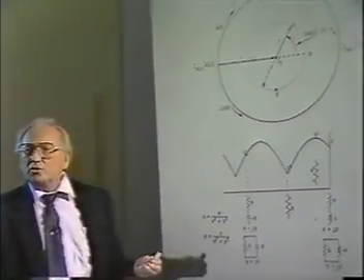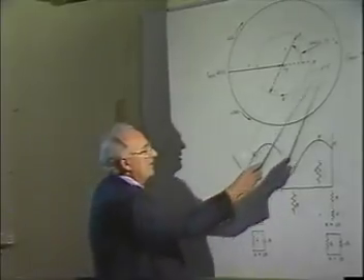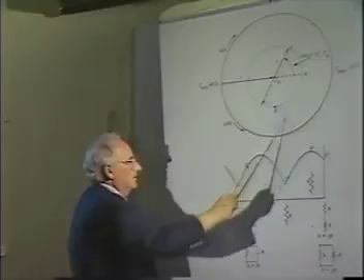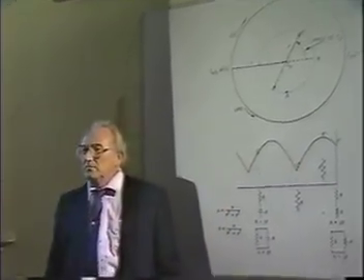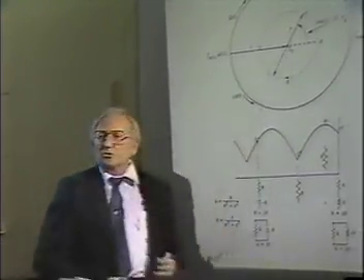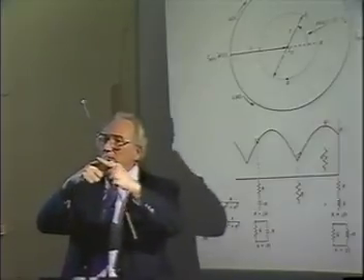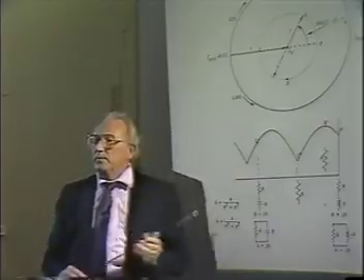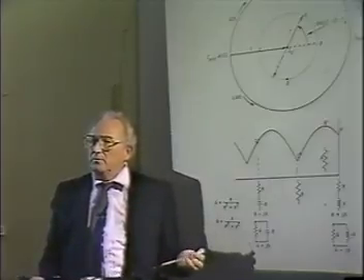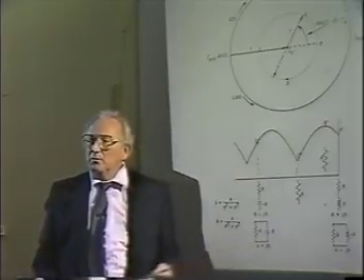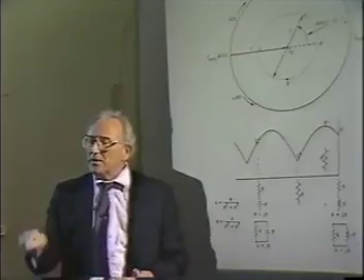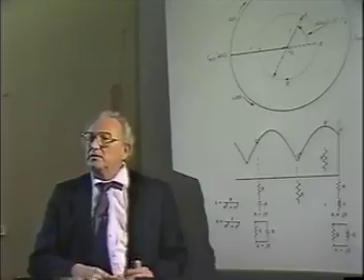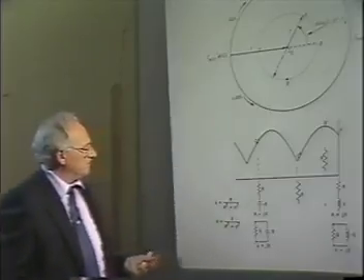There are other circles on here which we're not going to get into today, but they start over here and they'll come out like this. Those will be the reactance circles. You'll have the resistance circles. Any place a reactance circle and a resistance circle cross, you can read the two values right on the chart. We'll be doing that, and you'll be actually working problems. And when we do some impedance measurements in practice right here in the classroom, you will be required to plot these impedance values on the Smith chart.